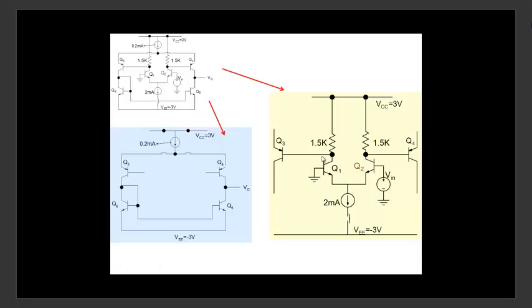That's fine. How much will be the voltage at this particular point? There will be a bias voltage. Can we calculate the bias voltage? 1 milliampere here will flow here, and we can calculate what is the bias voltage here. We can also calculate, because of this V in, what is the differential voltage here? Both of these things we can calculate. Common mode is 0. What is the net differential input voltage V in? So you'll get some part here and some part here.